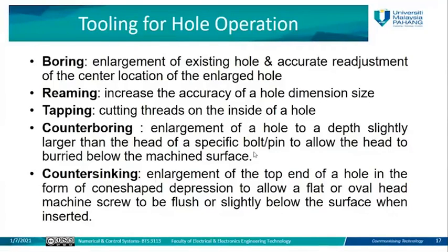So this is used to enlarge the existing hole with accurate adjustment in the center location of the enlarged hole. So for example, this operation we call the boring. Boring means enlarging an existing hole. That means you already have a hole, so you want to enlarge it and make the center of this hole accurate. Maybe the hole is a little bit off the center point that was decided in the design drawings. So you need to adjust the center, so you need to perform the boring operation.